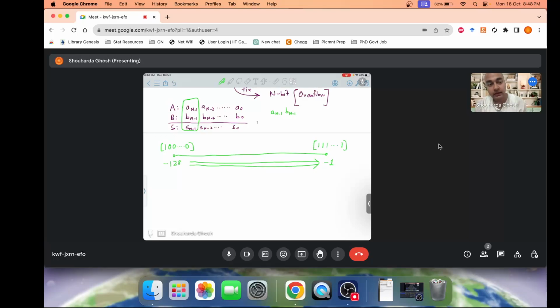So if you notice the numbers in 2's complement representation, negative numbers have MSB equal to 1, and the higher the total number of ones present in the number, the lesser negative the number is. The more zeros you see in it with the MSB being 1, understand that the number is highly negative. In case of positive numbers, it's the opposite.